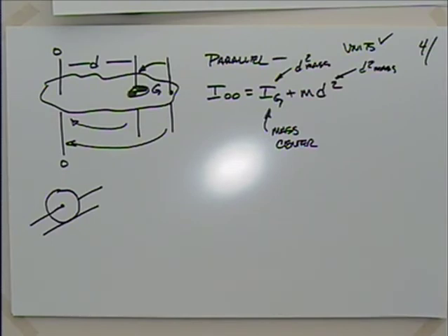Okay. So let's keep things really simple and think about your lawnmower starting to get spring. Things are greening up. Got to drag out the lawnmower, right? If you got a push lawnmower, single cylinder, we got a single cylinder 4-stroke engine on that lawnmower. It's producing power 25% of the time. Well, I like to mow grass 100% of the time, right? So how am I able to mow grass that other 75% of the time? It's with the flywheel, right?